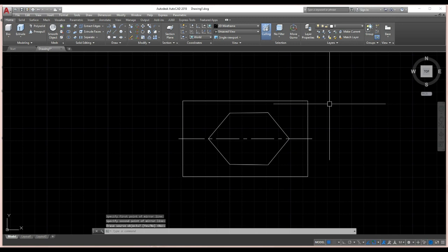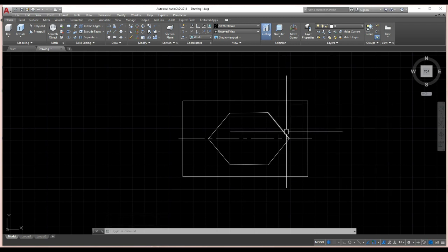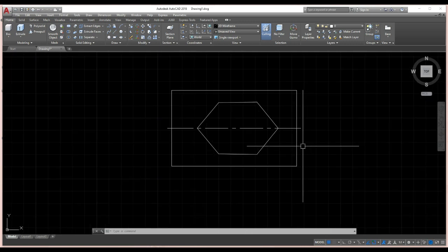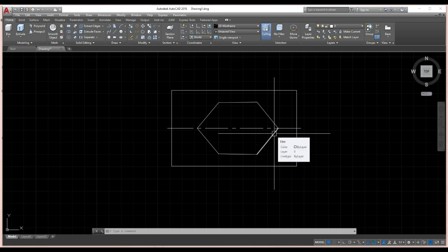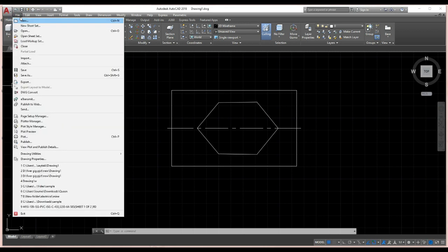This is the simple profile we have created, and we will create the program on this curve profile. If you don't have any model, it doesn't mean Powermill can't create a program. Powermill helps with single curve or multiple curve programming. But we save this file in DXF format. How do we save it? We go to File, Save As.